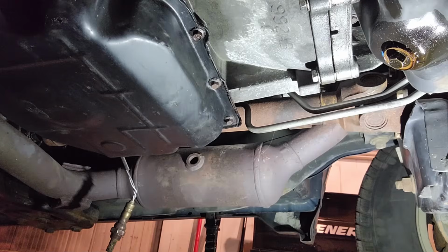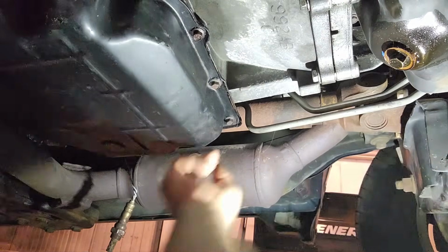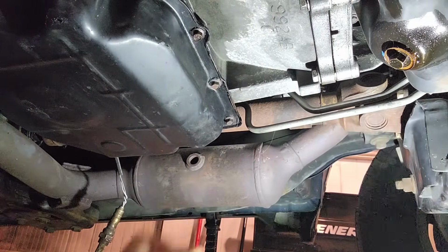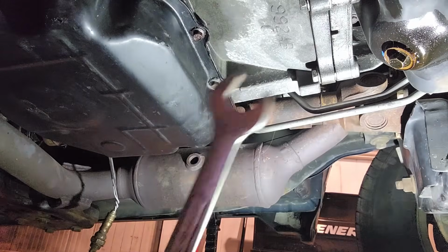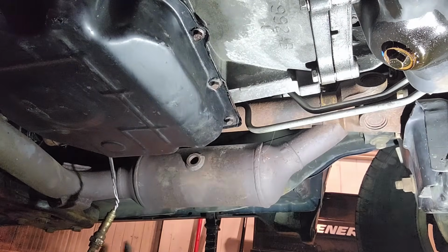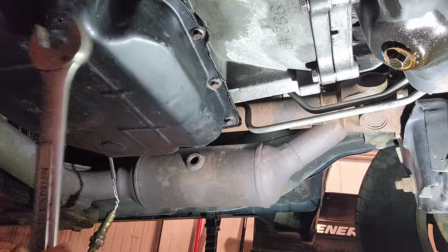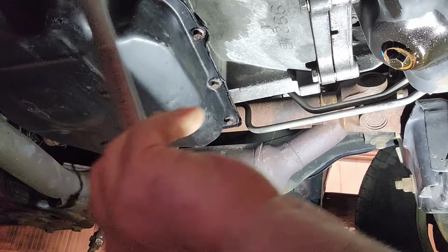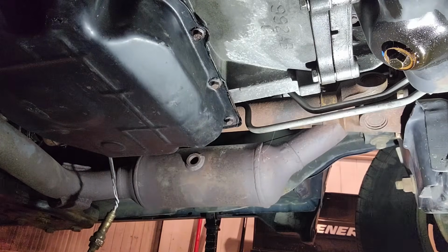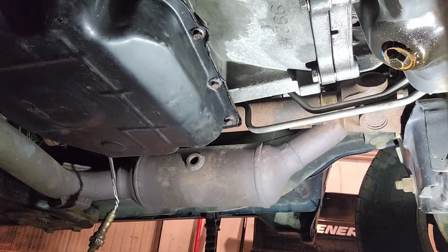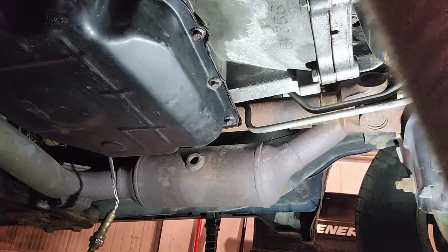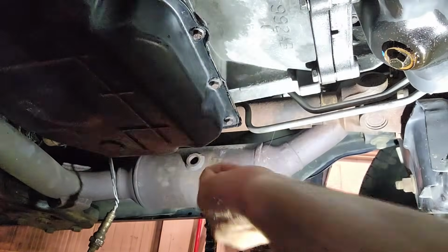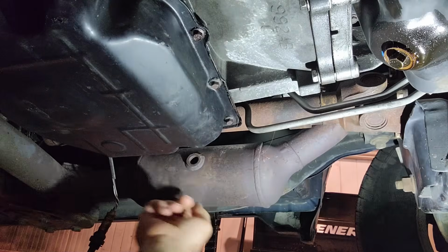Okay, guys. This is the driver's side. I took the O2 sensors out. I just took a 7/8 wrench. Same thing, a good Airco tip. Hit these hard and fast, cold. No lubricant, just one good sharp twist whenever they're cold, when the pipe hasn't been run recently, and they both came right out. This one's on an angle. I'll show you when we get to the other one, and it still came right out.